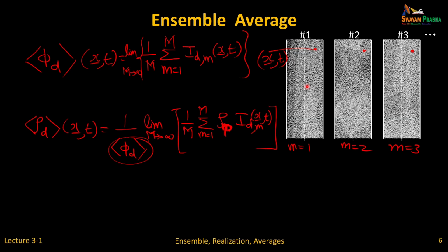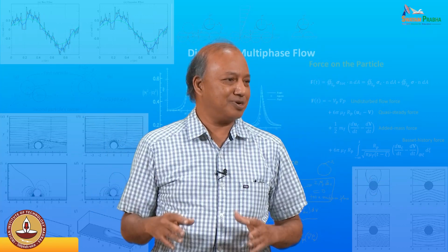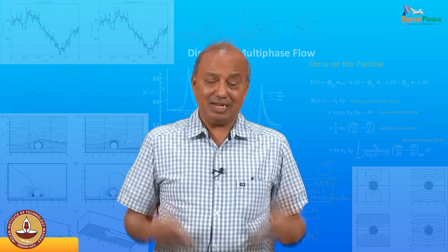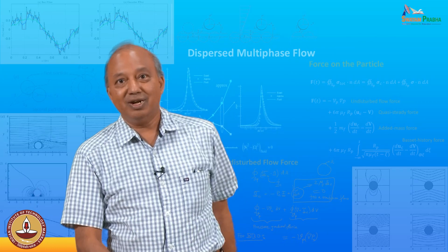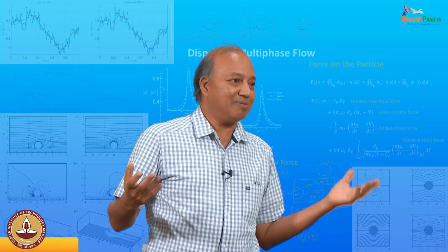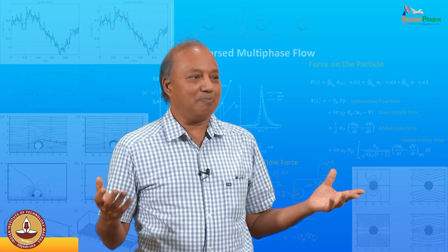Okay. The other thing I was talking about is the ensemble average. Ensemble average is nothing but you can pick a point and you average over all the realizations. Now, in this simple example, it's a uniform distribution with some structures, the way I've drawn it, and I don't know where the structures are going to appear. So when I average over a gazillion realizations, sometimes I will be in a cluster, sometimes I may not be in a cluster, but it doesn't matter where I pick the point.